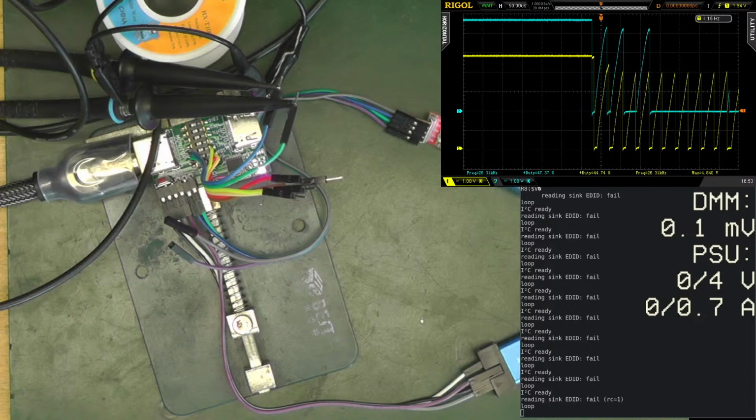So in case I forget to set I2C RC to the code, but I still fail and I go to the end, then it still is fine. RC is equal to, so the setup is wrong. And the setup is wrong when the lines are not pulled high, because they're not pulled high fast enough. I think that's it, so yeah, it's the I2C master setup.